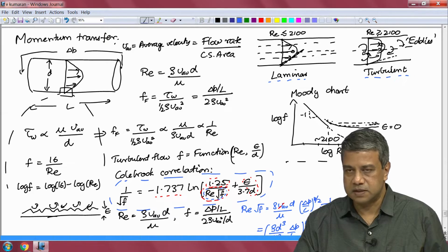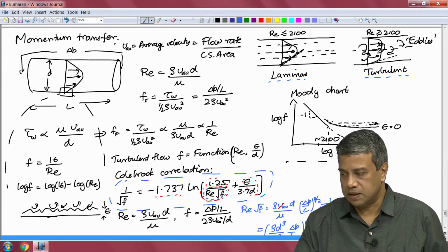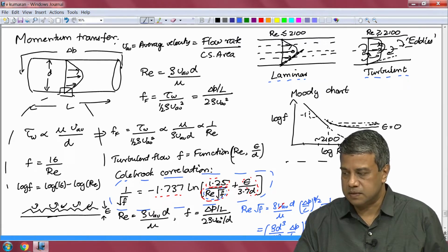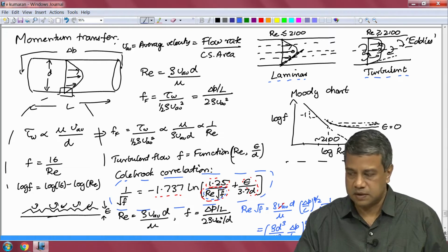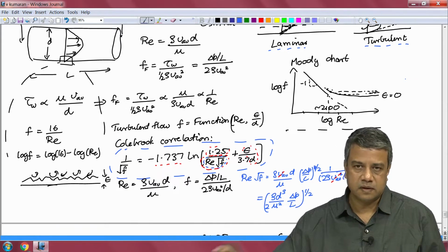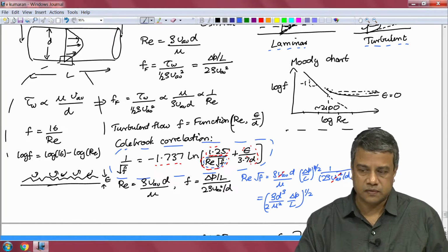These velocity fluctuations are due to the correlated motion of parcels of fluid called eddies, and these eddies transport mass, momentum and energy across the flow. The transport by eddies is much more efficient than the transport by molecular diffusion, because of which the transport coefficients and the friction factor are higher. The friction factor is a scaled momentum flux. So, the scaled mass, momentum and energy fluxes are much higher than those for a laminar flow.